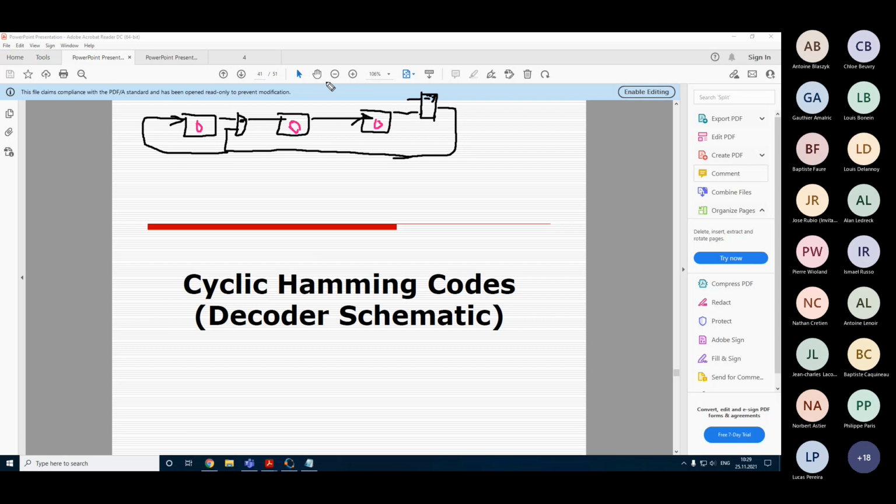Then we get some data bit. For example, let it be 1. So what happens in the next time interval? What happens is that these zeros are shifted out. Basically, they go from inside to the outputs here. This one, this one goes here, and this one goes here. So the contents of this flip-flop is read.